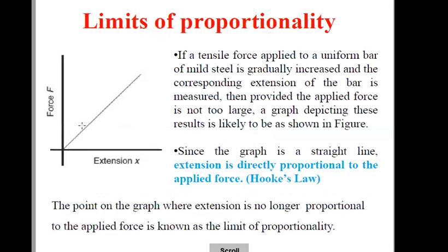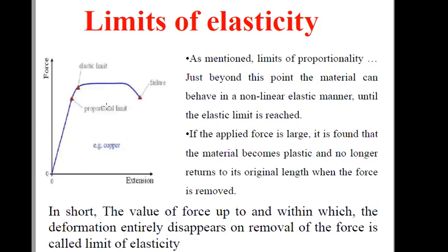And the next is, this is the curve. It will be a straight line if it always follows Hooke's law. But this doesn't happen. This will be your elastic limit. After this, it will either go something like this, in reality, and the curve will look like this. So this is your proportional limit, this is your elastic limit, beyond which it will not regain its shape, and this is your fracture point, meaning it will break.